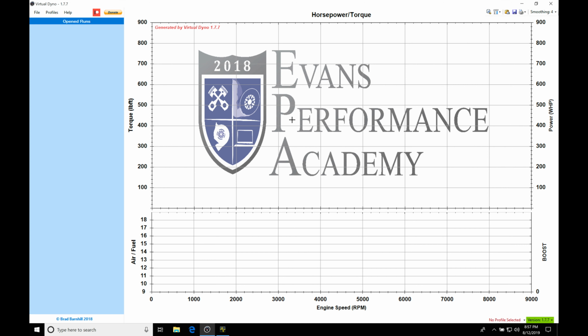So what we'll find is that if we're reviewing our data in the AEM Data software, we're able to export the data out and import it into the Virtual Dyno software. The Virtual Dyno software can't use that native file, which is a .it log file from the Infinity. It has to be converted into a .csv. And we're going to learn how to do the export process from the AEM Data so we can import it here to the Virtual Dyno and do our plotting.